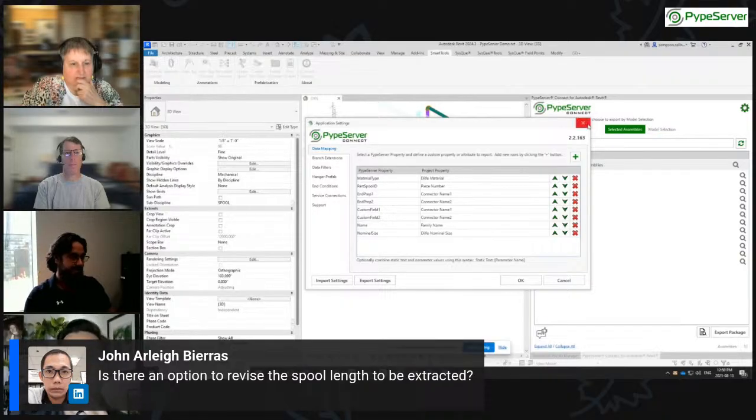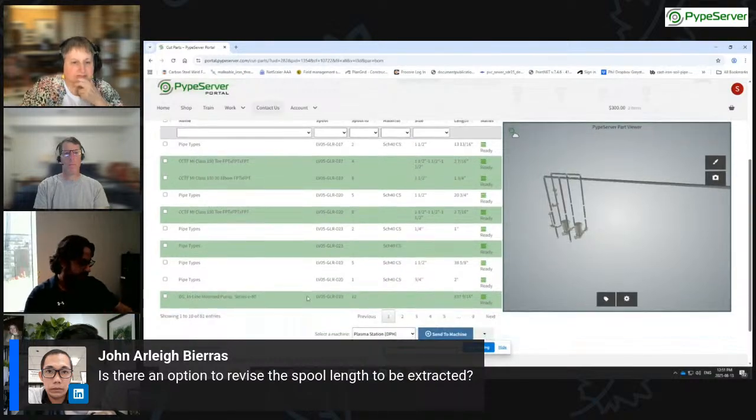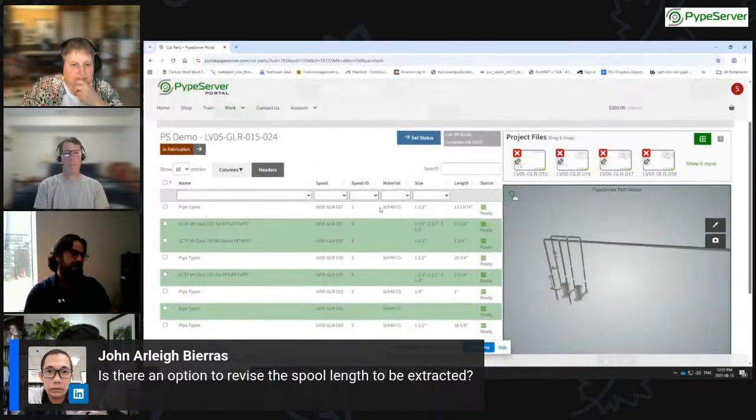So by doing that, back on this screen, it's reporting schedule 40 carbon steel. This is how we know it. Now we can nest everything through all of that material. So if I had copper here too, we can go and cut through schedule 40. We can cut through all of our copper because we've set it up that way. Same thing with the sizes. We've made it more applicable for sizing. So the way that we actually order things.